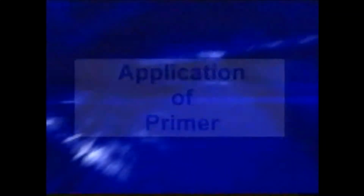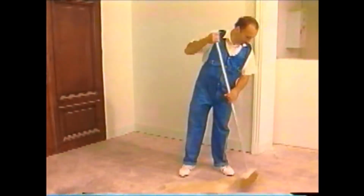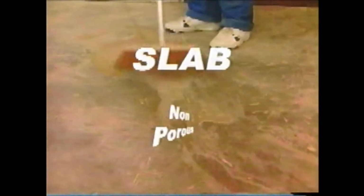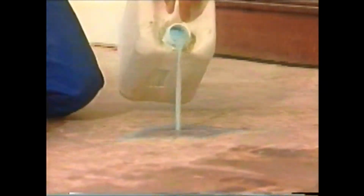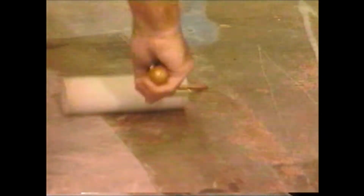Once the examination is completed and the preparation work is done, the primer may be applied. This shall be specifically adapted to porous slabs, normally absorbent slabs, and non-porous slabs. Before application, sweep and vacuum the slab carefully. A suitable primer will improve the bonding of the adhesive to the subfloor.